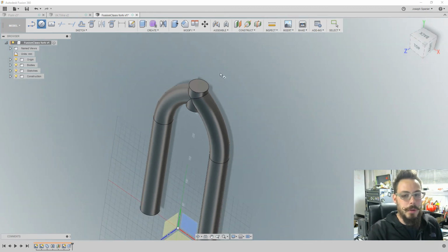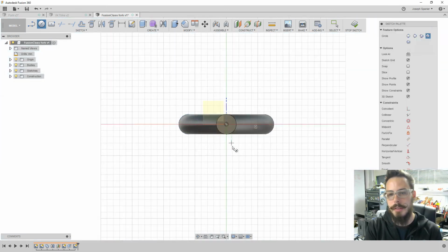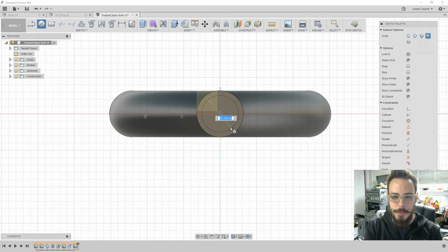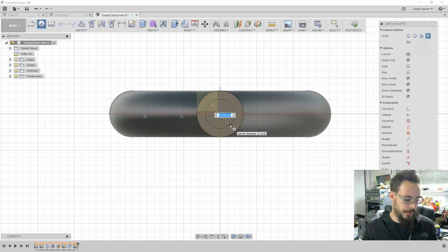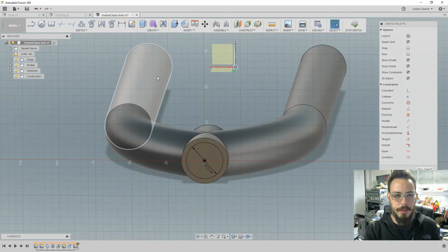So this time, I'm going to create the sketch on the face of existing geometry instead of creating it on a plane. And that's totally acceptable. You do it all the time. And it's really handy when you're creating square things, because then you always have a planar geometry to start a sketch on. So we'll dimension this as 25.4. Enter to finish out the command.